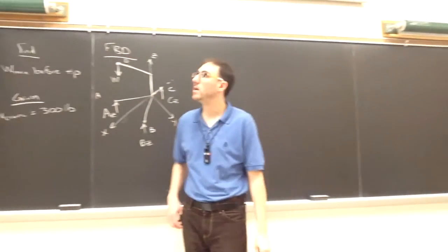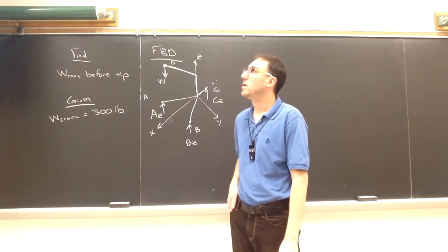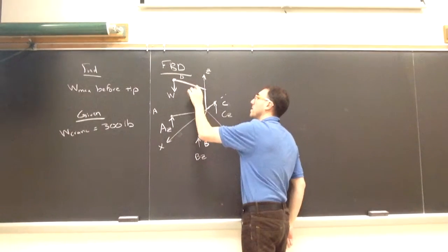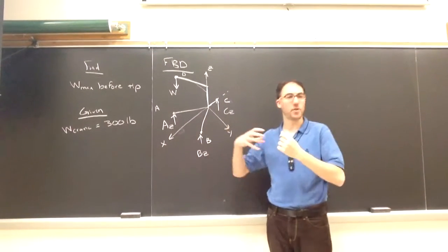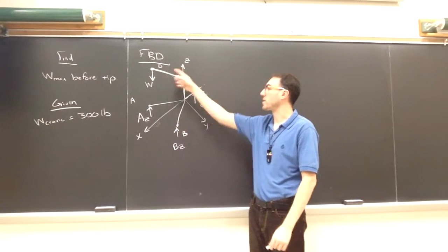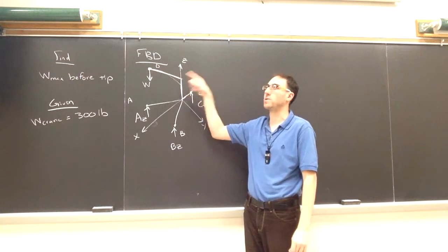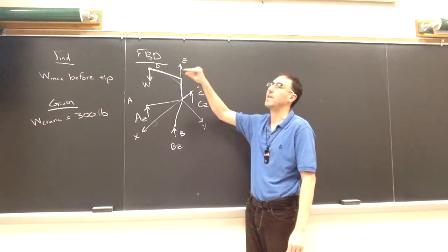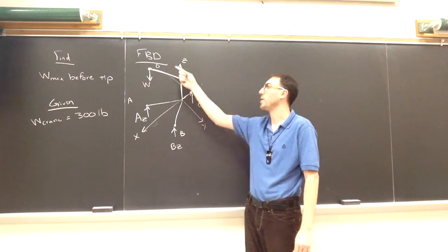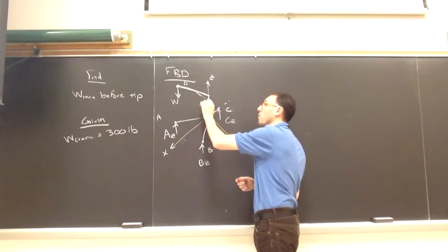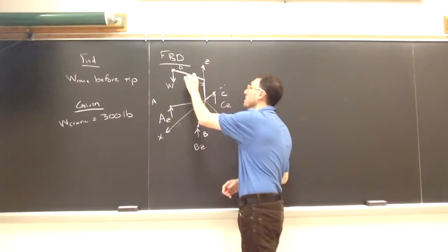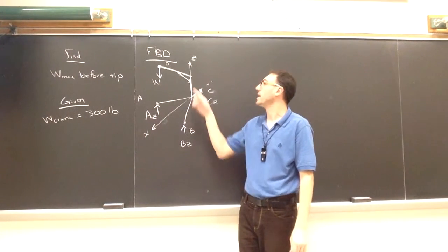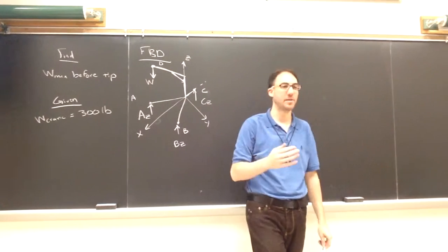What's that? Looks like a shock from the z-axis up, the 30-degree thing? Well, that will be included. That's part of the crane in my picture. So if I'm including it, then I don't include the force that it would impart on that boom arm out top. But you're right, if I did not include that piece of it, then I would have a force here and a force there from that shock. So for simplicity, since I'm not asked for what the force in the shock is, I can just include it here and then I don't have to deal with it.